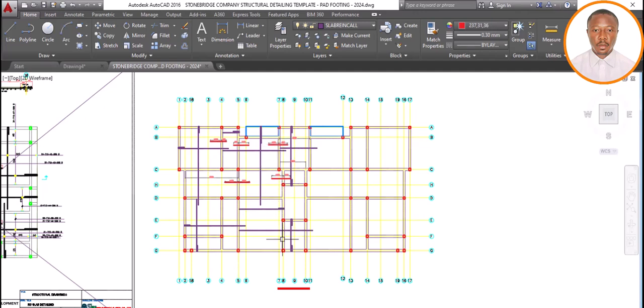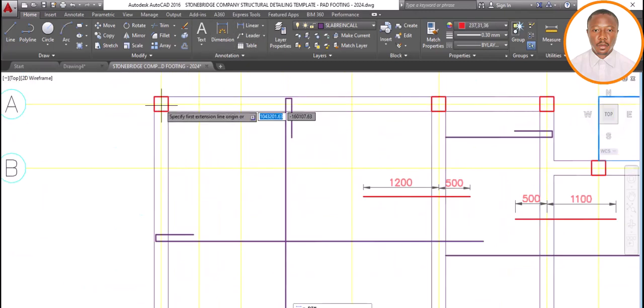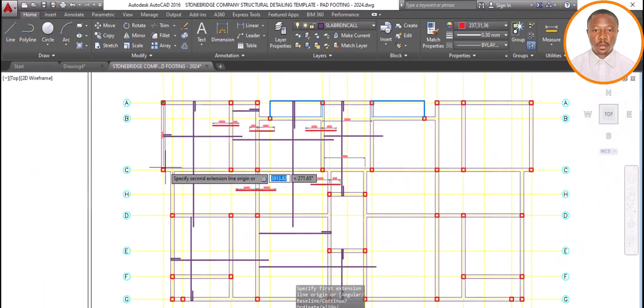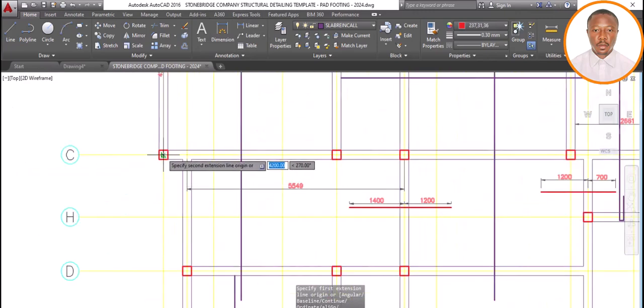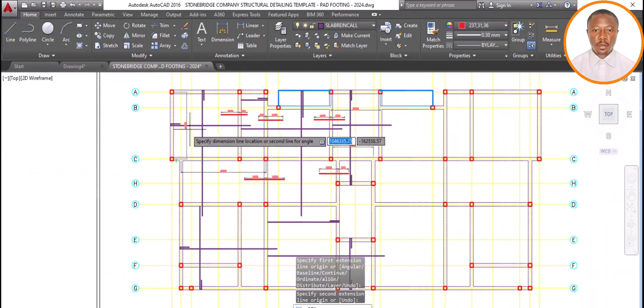This one takes care of this one here, and also jump to this one, because they have the same thing. All right, so vertically we are done. So now horizontal top reinforcement, let's check. Let's take our dimension and come here from the center point of the beam to this place.